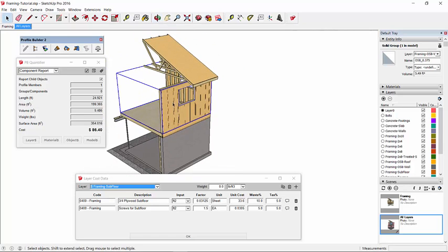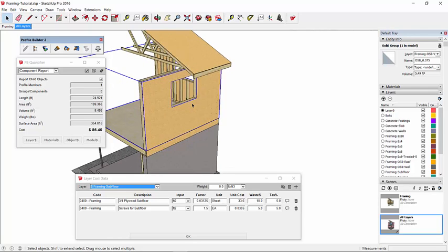If you're interested in the reduction from the openings, you'll want to model the sheathing in a slightly different way. I would recommend just modeling it from a rectangle for each section of wall and then extruding it out the thickness of the wall. Then any openings that you cut in it will be reflected in the total area calculation.